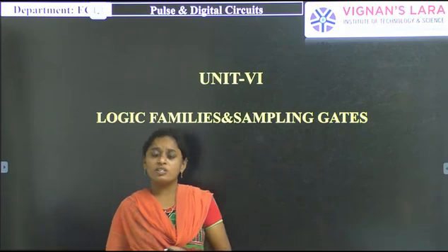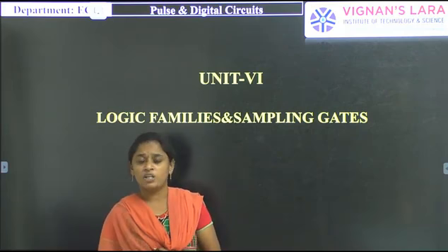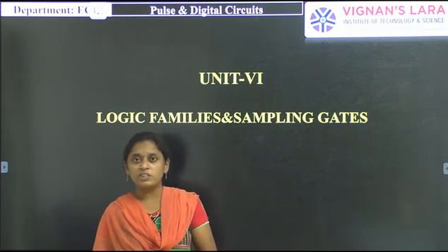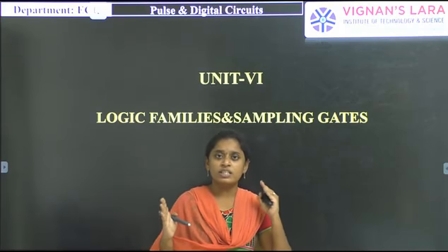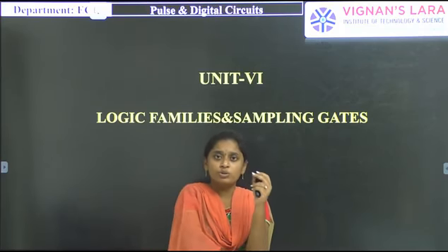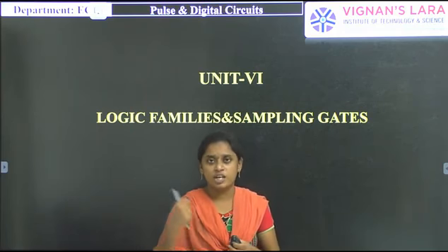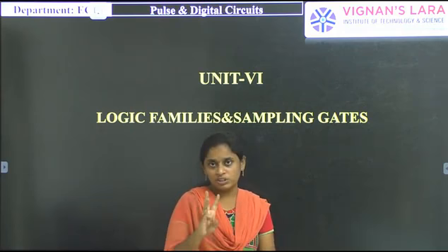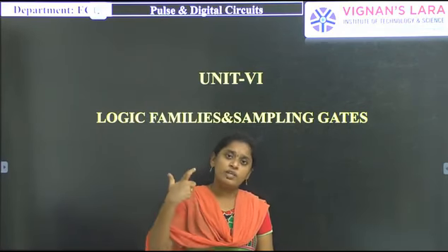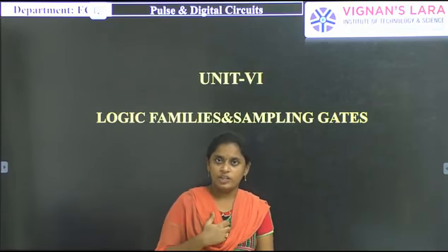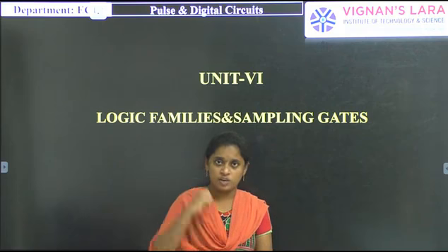And there is another logic family, that is the Schottky TTL logic family, which comes under the non-saturated logic families. What is the difference between TTL and Schottky TTL? The only difference between these two is that in the TTL logic family the transistor goes to the saturation region. We have three regions: active, saturation and cutoff region. In the TTL logic family, the operation is performed in the saturation region only.